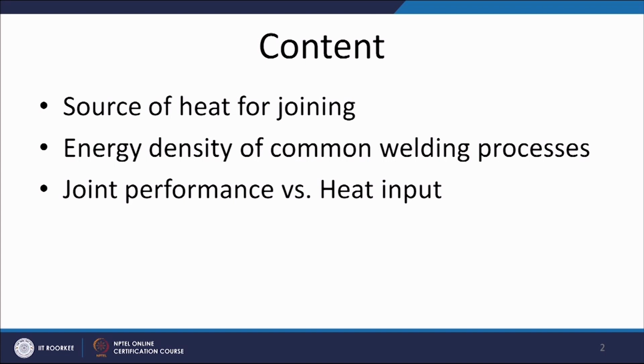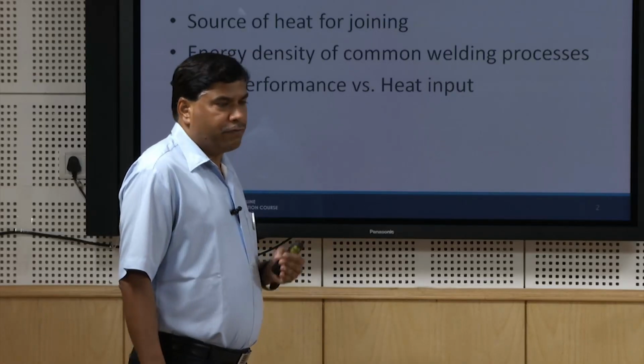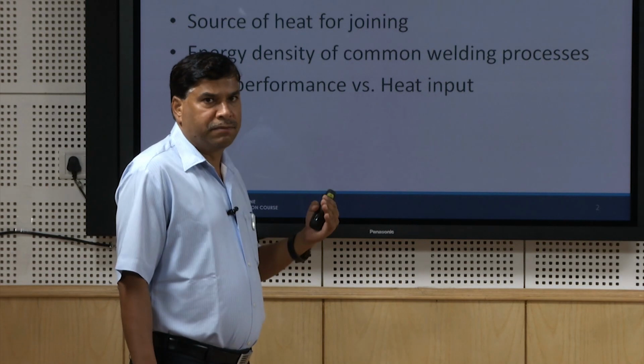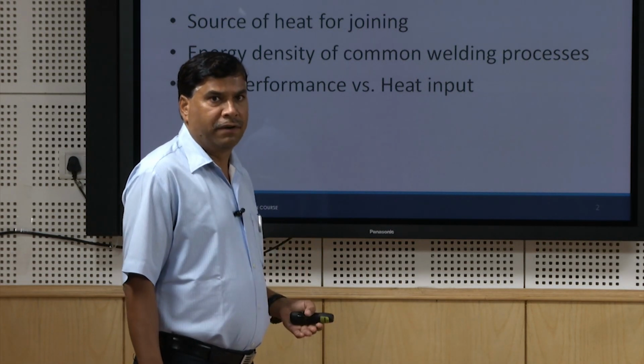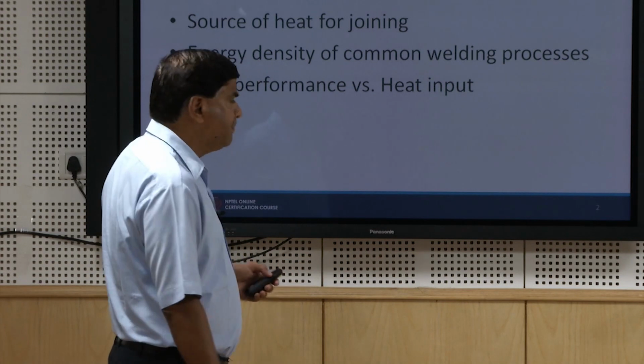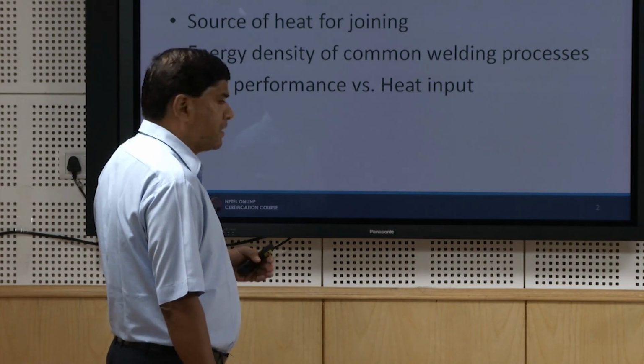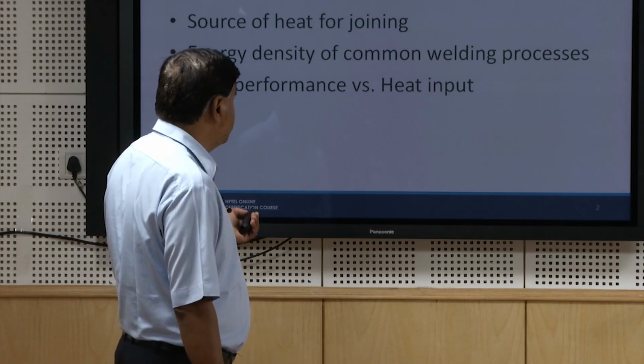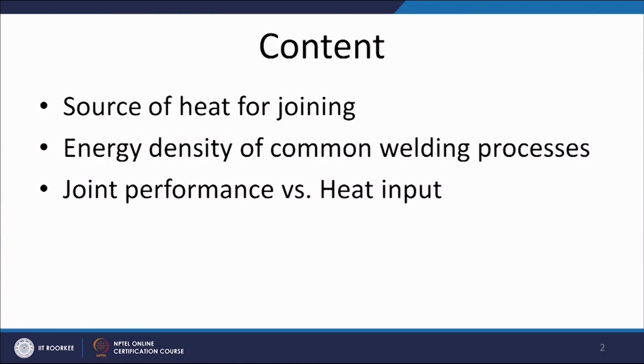Energy density associated with the heat source is very important, because it determines the amount of heat actually required for the given purpose. Like, say, for fusion welding, the higher energy density process requires less heat to be delivered for facilitating the fusion of the fixed surfaces as compared to the other low energy density processes. Energy density is very important from the welding and joint performance point of view. That is why we have to see how the joint performance is affected by the amount of heat being delivered.